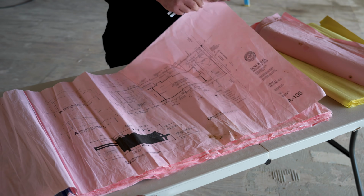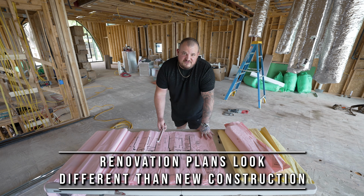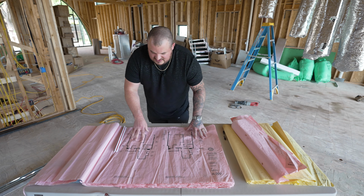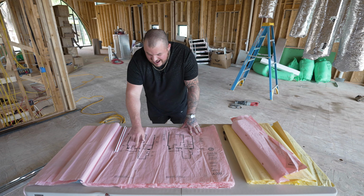But let's continue. When you're doing a renovation, it is going to be different than new construction. On a renovation plan, you're always going to have a demo plan. So what this is, it's showing you the existing structure with different dashed lines of what you're removing versus what you're leaving. And then you're also going to have a proposed plan. This means what you need to build.